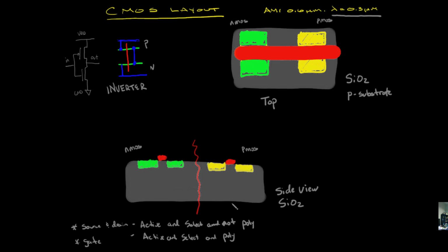We are also going to have to define the select layer to select the region that is going to be N and P type material. Has a much smaller footprint, and one thing that's important is the gate for the P-type has to line up with the edges of the select layer. We don't want to have any holes in our design.